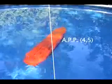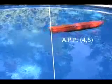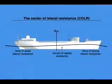We can see that the apparent pivot point of a ship trimmed by the head with headway is more forward, and the apparent pivot point of a ship trimmed by the stern with headway is more aft. The field of pressure, bow wave, and the stern sub-pressure under headway shifts the center of lateral resistance towards the area of higher pressure.